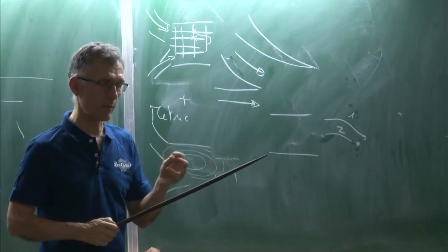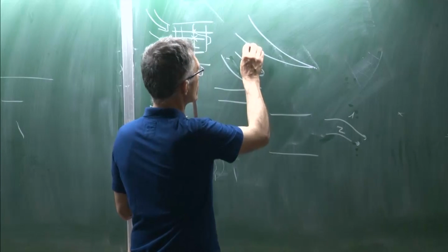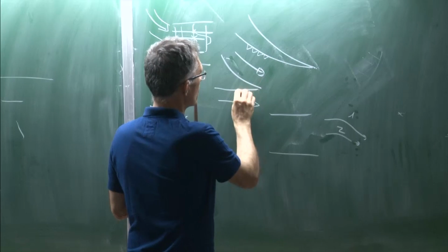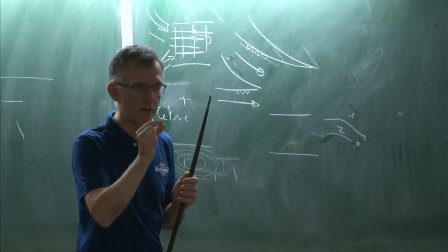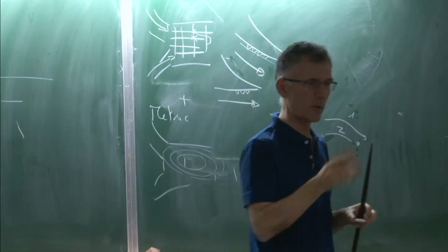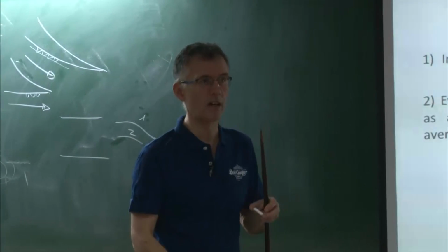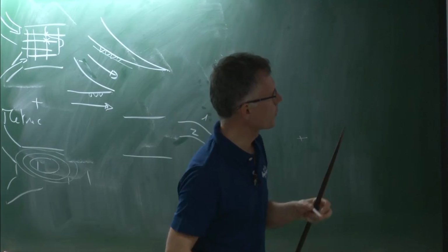How do you get the same mistakes? Well, you should have the same y plus. All the points, in every passage, should have the same value of y plus at the first point. Not a very small value, but the same. You see right away where the metric begins to be important, because that's a strong statement that you just need the same values of y plus. So this is what was done here.